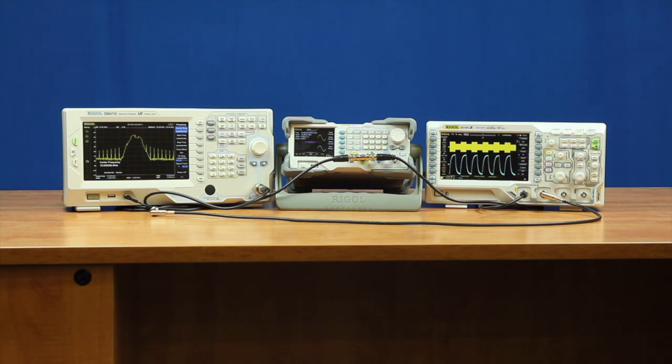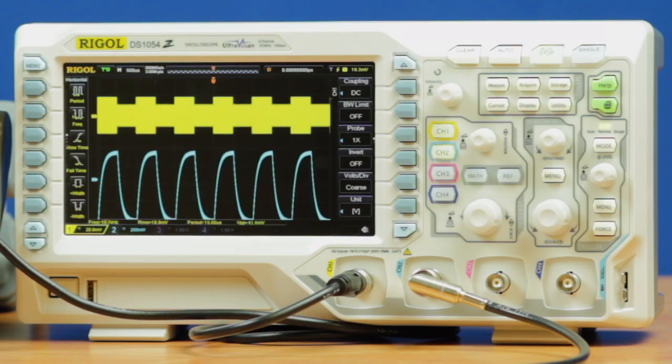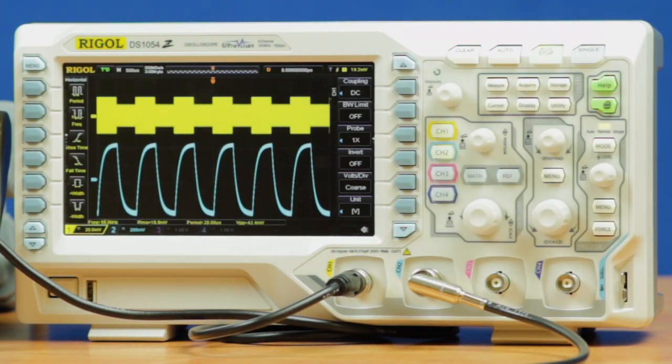And now we've taken a slightly different connection scheme, and we've hooked up the demodulation audio port coming out of the DSA 710 and have it going into channel 2 on the scope, so we can see the bit pattern, in essence the ones and the zeros. So here we have, in the yellow on the top, the carrier, the amplitude modulation. We can see the spans of 500 microseconds each, where it's high and low. And then in the blue, we can see the demodulated zeros and ones coming out of the analyzer that are coordinated perfectly in time.